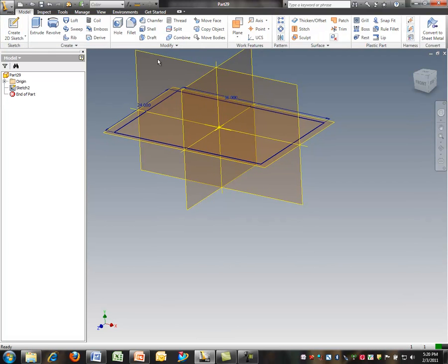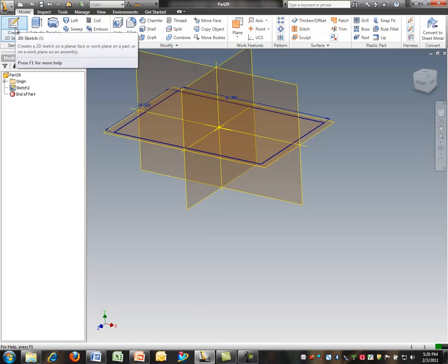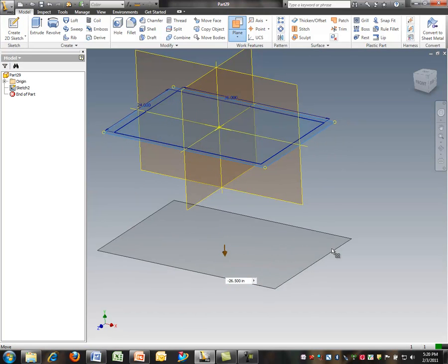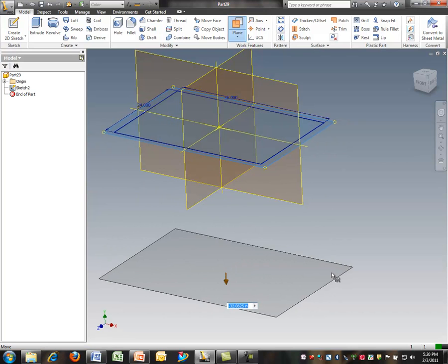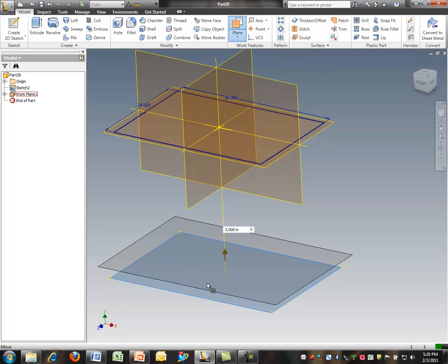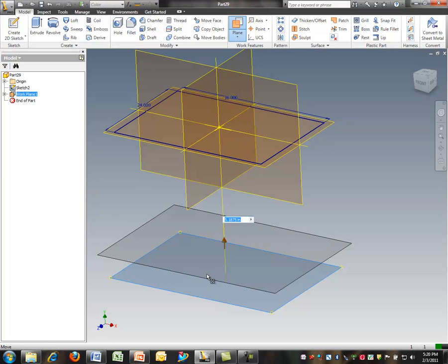Let's finish that sketch. Next thing I'm going to do is create a new datum plane. Let's make a new datum plane that represents the very bottom of the frame, and that bottom of the frame will be 32 inches down. Again, that puts me into the middle of the frame member. And now I'm going to create another datum that will come up this direction by, let's call it, 4 inches.